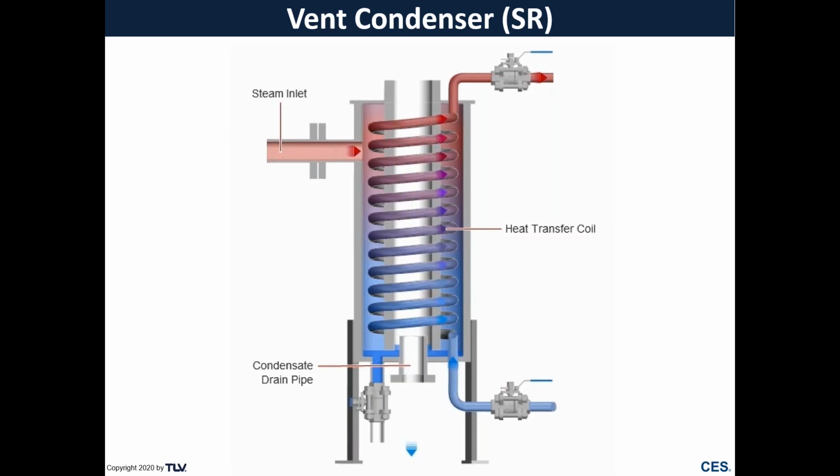The design does allow for that excess steam to run through that center vent in the condenser and be routed to the roof or wherever the vent is discharging. So at that point, we would condense everything the condenser is capable of condensing, and the remainder would be sent up the vent.